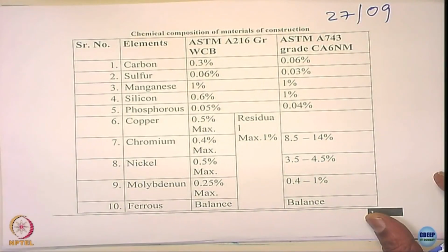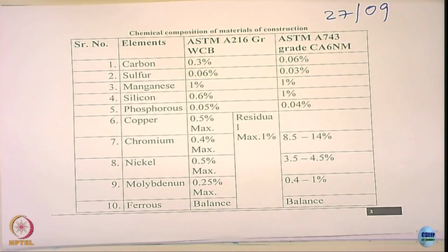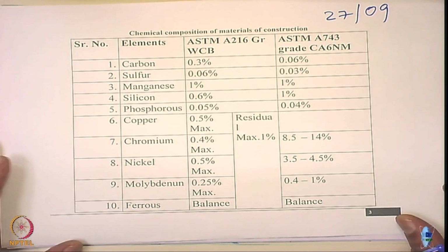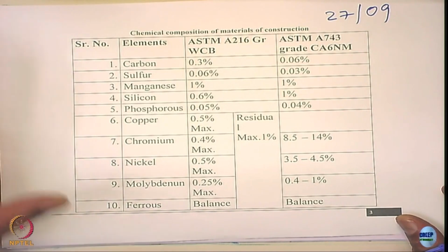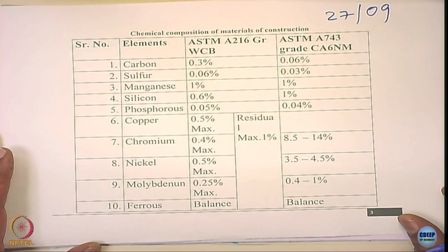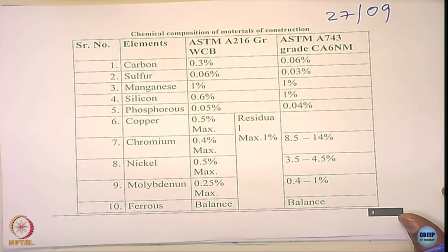So one of the things that they can at least look at is to monitor the thickness of the pump and see what happens. So that is one thing you can do. The other thing you can do is not to start alternately, but at least run one for 1 week and keep the other one dry, so that the liquid does not corrode it at all. Otherwise you are simply corroding both of them. So what was done was they advised that, okay, please do not start alternately, at least run one for about a week and keep the other one dry.